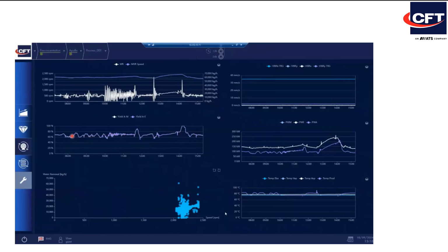What does a 60% efficiency mean? It means, in a very simple explanation, that out of 100 kilowatts you are purchasing from the electrical grid, only 60 kilowatts of those are transformed into compression of the vapors, and the other 40 kilowatts are lost. So it's a very important parameter. On the right-hand side, you see how that efficiency was generated, as we said at the beginning, simply with the relationship of the electrical energy absorbed by the motor of the compressor and its ratio with the energy transferred to the steam, which is mass flow rate times the enthalpy gap.